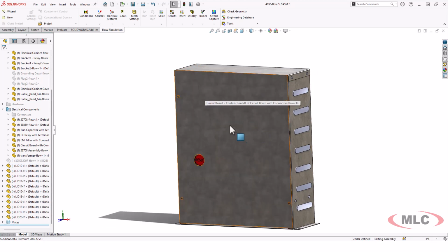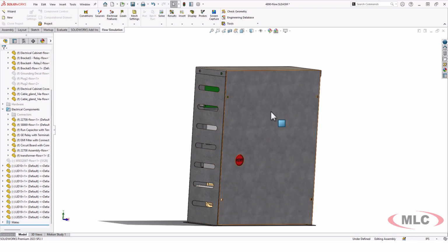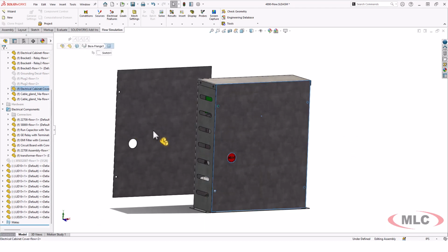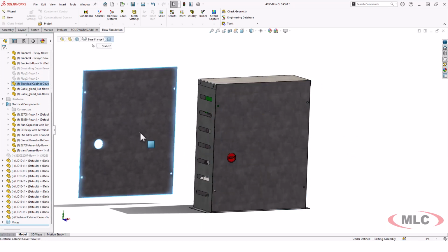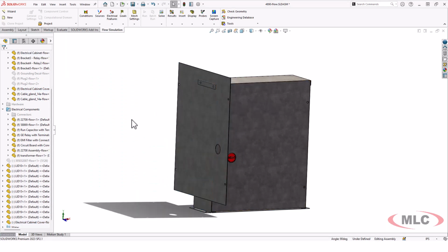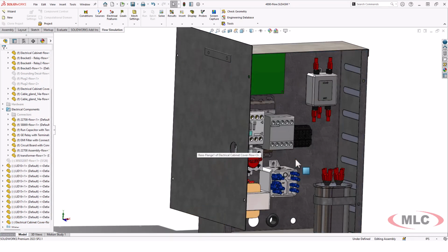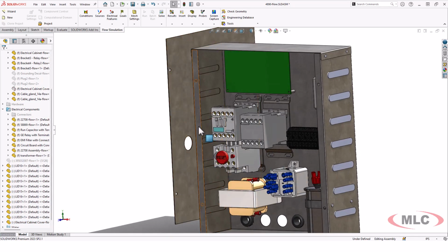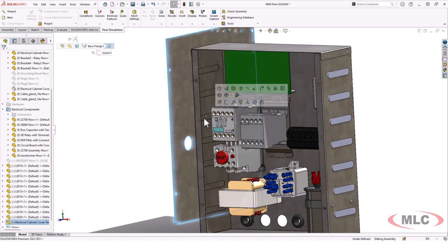Here's another method you could use to close these in. You could just take any part, like this front panel, just grab it, made it into place, and there you go. We've got a lid. Now, is this a good lid? Sure, sort of. Couple problems with it. I only have one face, so it's easier to define where the lid boundary condition is, but I can't individually specify or measure flow through each of the individual lids because it's one big lid. So that's some pluses and minuses.